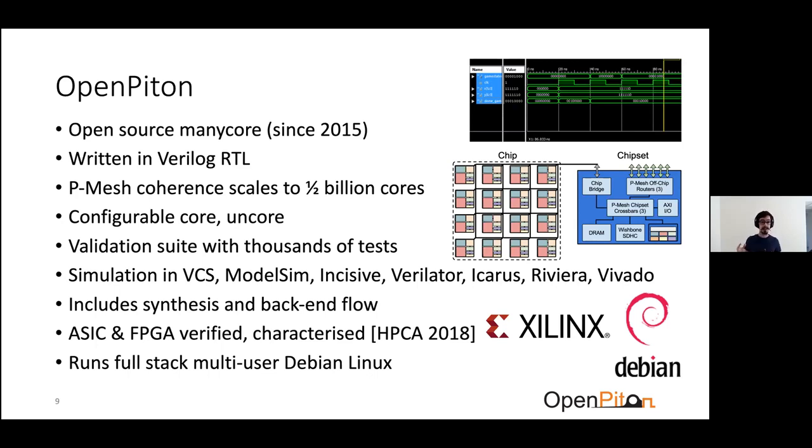We have actually taped out multiple real chips based on this platform, and there's even a characterization I'll talk about a bit more. The chips or FPGA prototypes themselves can actually run real Debian Linux. So you can take existing software and test the scalability, or make minor modifications to software to support new hardware features that you add, and then test them in a real OS-capable environment.